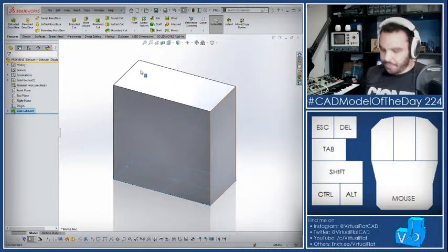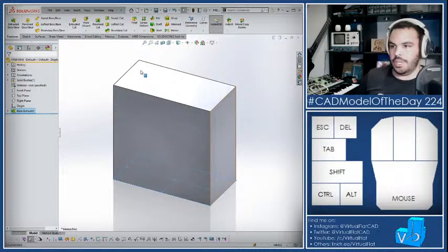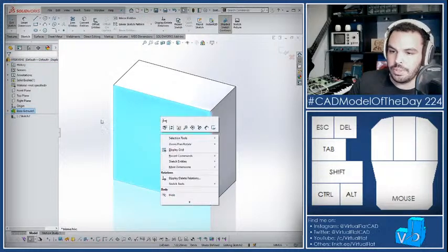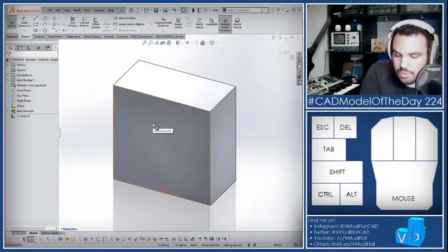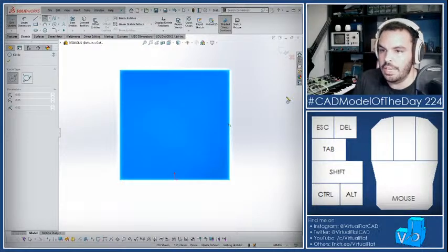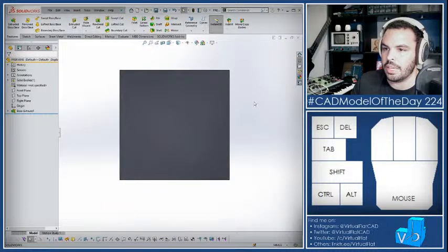Like this. So I'm just going to grab the diameter of that. Looks to be 120 millimeters. So I can just sketch there. And, oh, actually, I learned a cool trick. So I need a circle right on the center of this face, right? So check this out. I'm just going to back out of this sketch for a second.